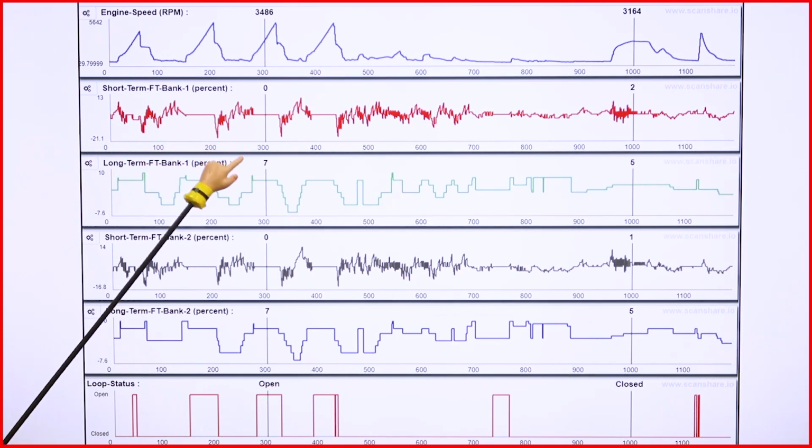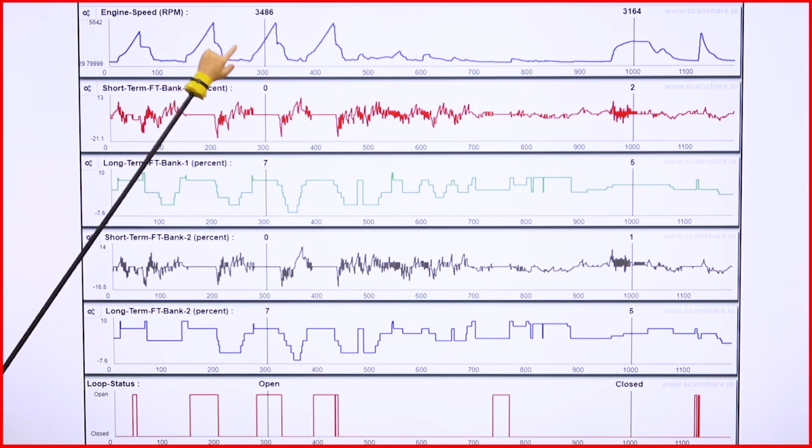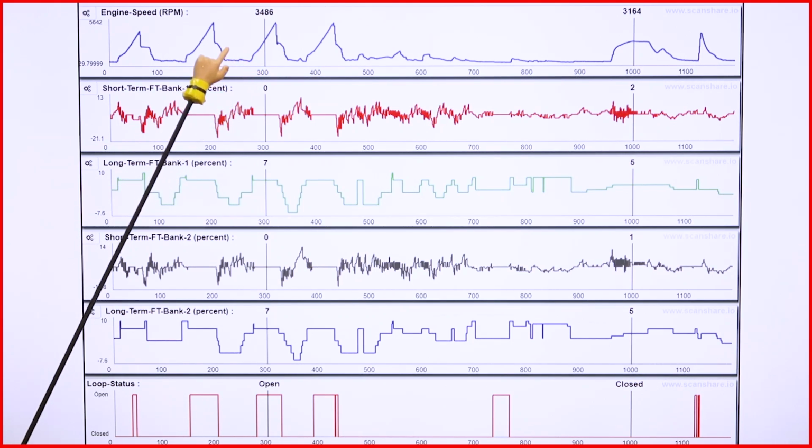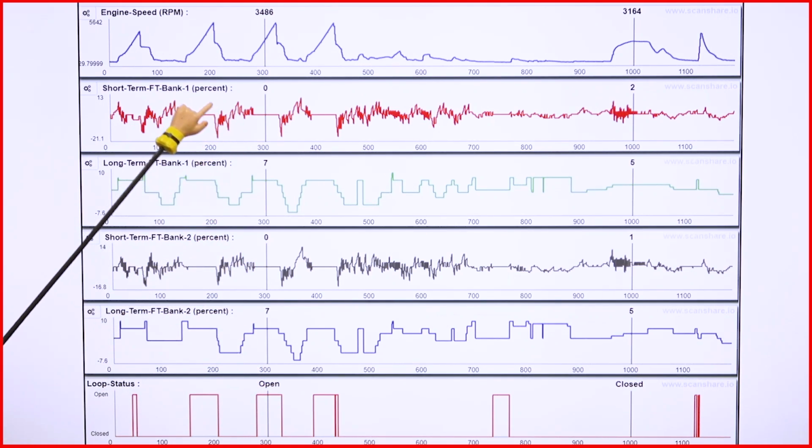We've got to get out of traffic here, or get across the intersection, something like that. We're going to go back to our pre-calculated fuel delivery pattern here. And so if we look on the bottom, it's open loop. When we're in open loop, we really don't care a whole lot about fuel trims, or they typically go back to 0. In open loop, really all bets are off on the fuel trim side.